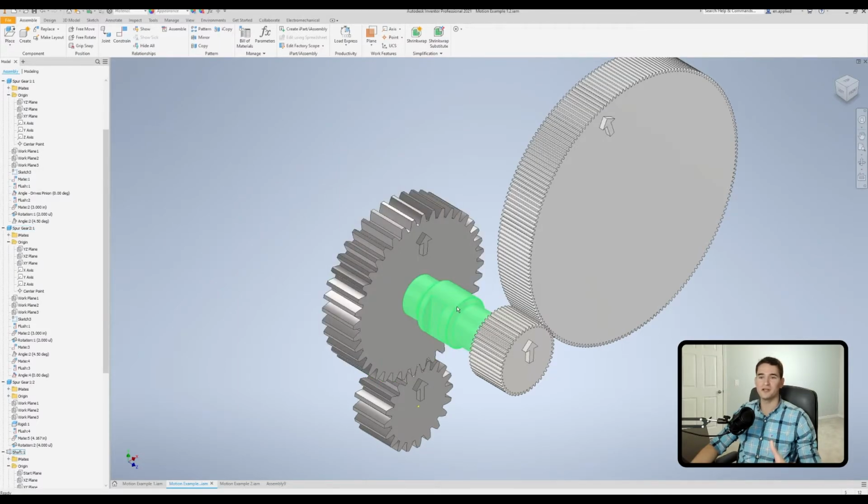And then on the other end of the shaft, I fixed a smaller gear, okay? This smaller gear rotates at the same rate as the shaft, which rotates at the same rate as this gear here. And then we have this larger gear at the end that is being driven all the way through by this pinion. As this pinion spins, it'll spin this gear, which spins this shaft and this smaller gear, which will then finally drive this gear at the end that's only constrained by its axis here in 3D space. So it can freely rotate, but it's being driven by everything in this lineup of gears.